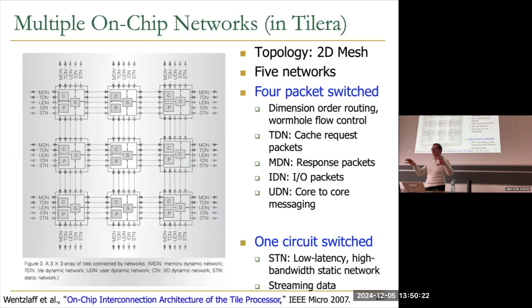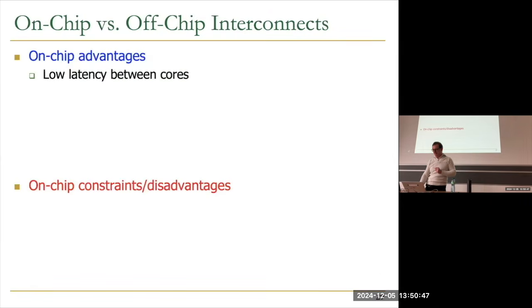But one of the deadlock issues is higher-level, protocol-level deadlock, where a request packet may keep resources such that reply packets cannot go through. If you separate these networks, then you don't have that problem, right? Does that make sense? I'm not suggesting every single deadlock will not occur, but at least that type of deadlock you don't need to deal with. And there are also other reasons to separate those networks.